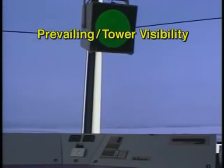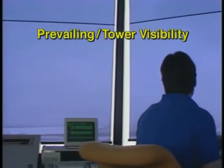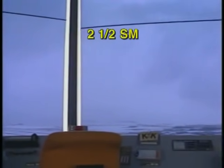Since the takeoff minimums are normally based on visibility, let's look at the various types which are reported at an airport. Prevailing or tower visibility is the greatest distance a weather observer or tower controller can see throughout at least 1/2 the horizon circle. It is measured in statute miles or fractions of miles.